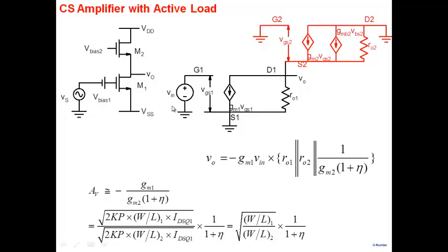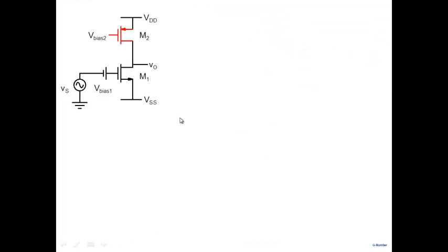And therefore the net resistance at this particular node becomes small. And if the resistance at this particular node is small, the gain developed at that particular node becomes small as well, which you will see in more detail a little later on. So the idea is that if you want to build large gain, then you don't use an NMOS, you use a PMOS transistor here.